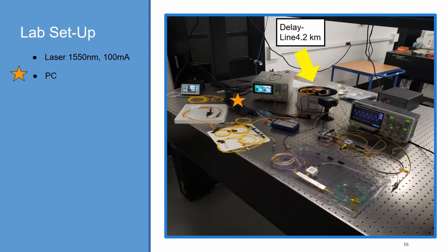Then we have a polarization controller, a variable attenuator, which attenuates power by some -20 decibels. And finally, there was the fiber optic splitter or coupler, which, without getting into too much detail, helps with fine-tuned measurements of the attenuation and being able to attenuate it in a more precise way.